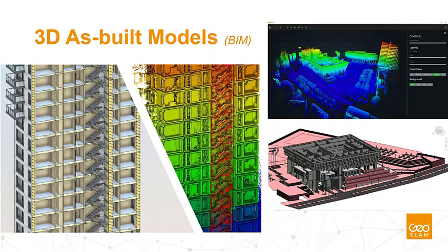We can bring that point cloud into our modeling BIM software, and then we can do some manual modeling just by simply using the point cloud as kind of an underlay. Or there are ways to do automated or semi-automated modeling using feature recognition and extraction tools. And we have an example of that I'll show you within our Draw software. It's called the 4CAD Revit plugin, and I'll show you what that looks like.